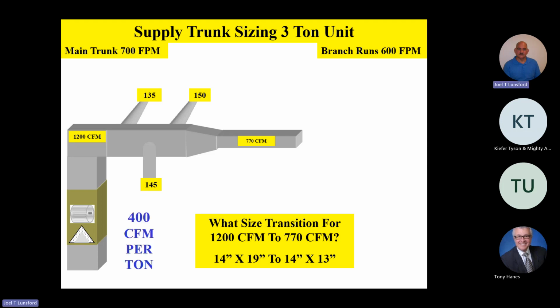So the next takeoffs we're going to do, we have 90. We've got a pretty small space, so we have 90 CFM at 600 feet a minute velocity. So take your velocity and go down to 90 CFM at 600 feet a minute velocity. And what size duct do we need to make that happen? 6. So I like your answer. It actually came up about 5.5.